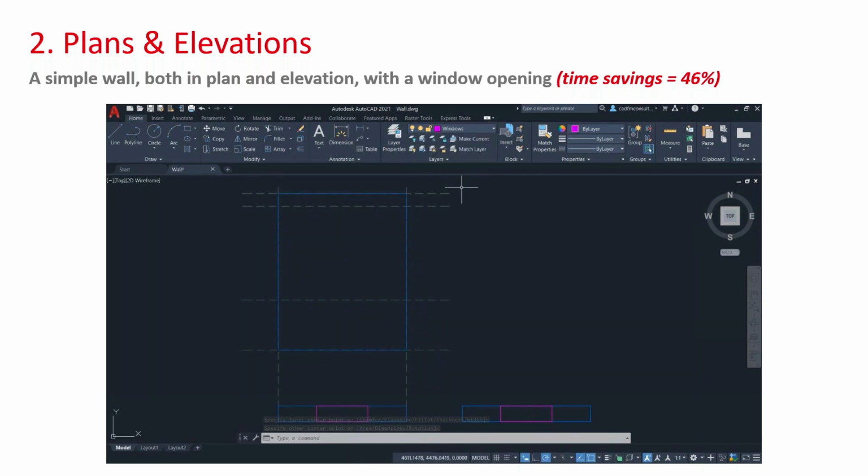I'll jump into the windows layer now, and what I'll utilize now is a little bit of polar tracking and object snap tracking, which I'm sure you've all utilized before. So I'll hover over that corner there, come up to the intersection with the construction line, and again hover over the other corner in the plan view and come up to the other construction line. There's the intersection, and there's my window representation in 2D. So that's all flat, and I've had to draft all of that manually.